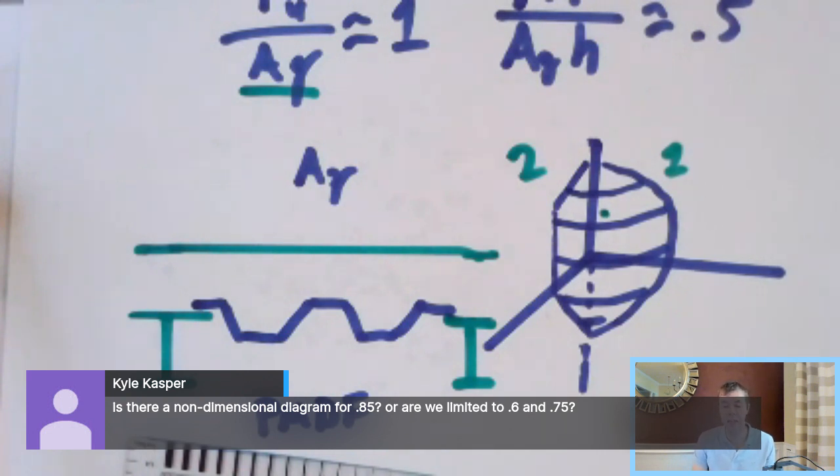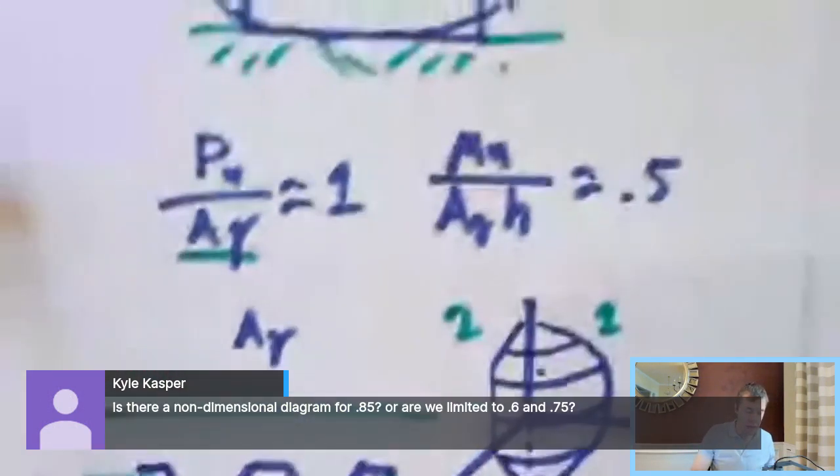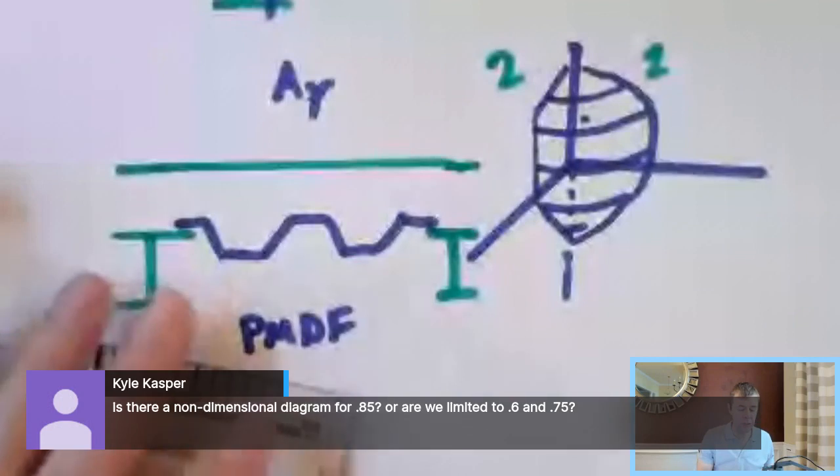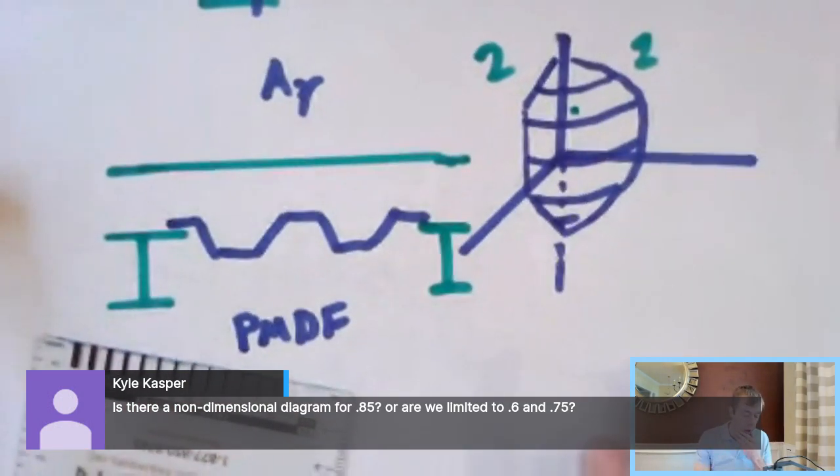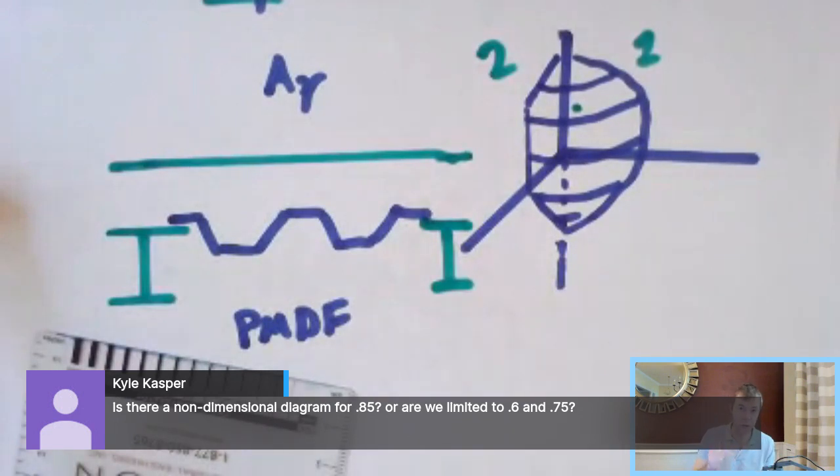In the case that you're in between a gamma of two different interaction diagrams, then you can actually linearly interpolate in between them if you want to. So you could take your answer from in between like a 0.9 and a 0.75, and you can linearly interpolate between the two. That's allowed and that can be done. I didn't show that to you because that's kind of an advanced skill, but that's what you can do if you really want to dial it in.